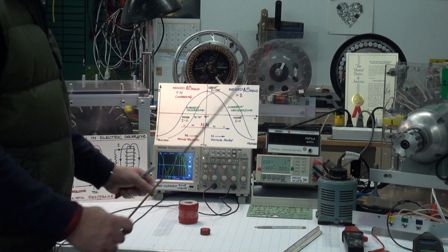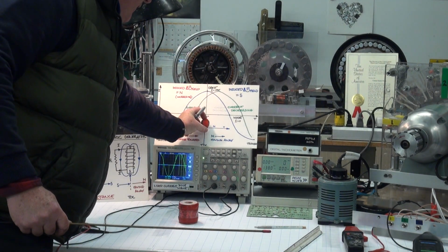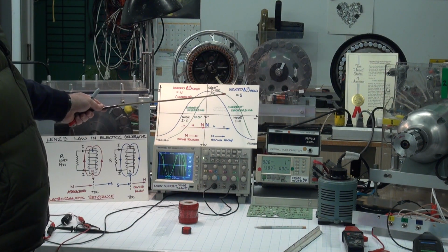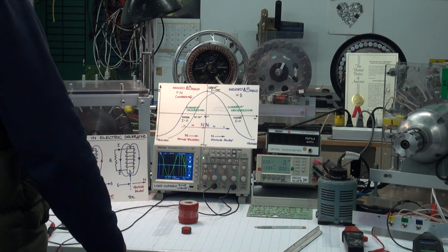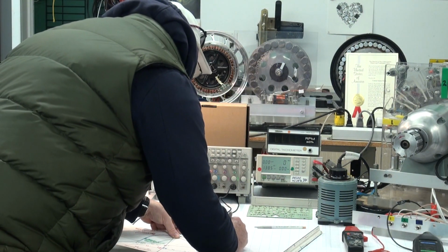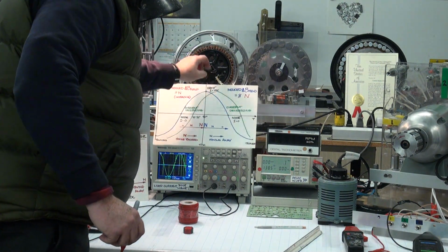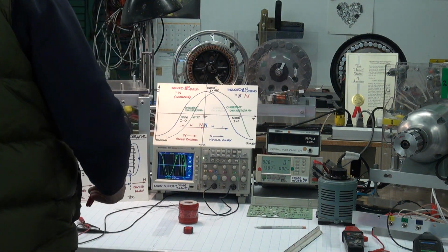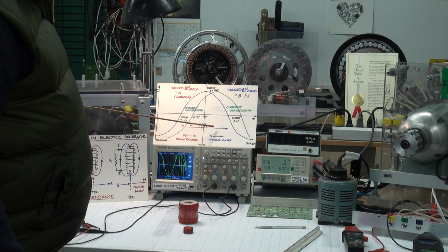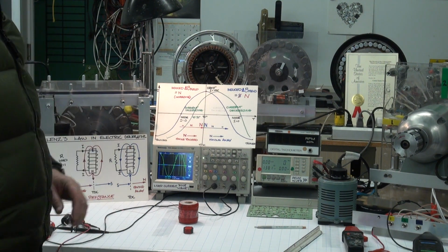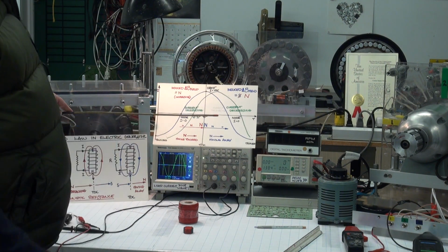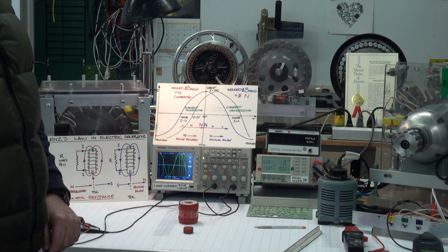So as the rotor magnet starts to move away from the coil's core, the induced B field in the regenerative coil is still producing a north pole magnetic field from here to here, which has the effect of accelerating and performing positive work on the rotor magnet that is now moving away.